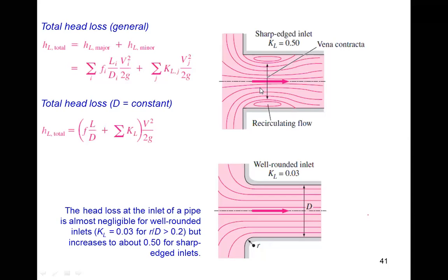So in the market, you cannot buy a pipe of any length. You get ready-made pipe only in lengths of about 20 feet. If you want to make a longer pipeline, you have to make a joint. A joint can be made either with the help of welding, or by threading, which you need a coupling for. I want to show all of them here.